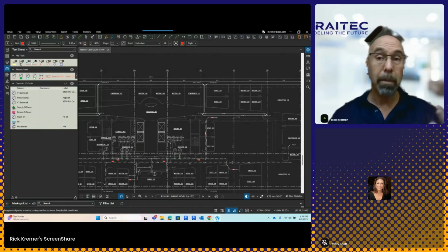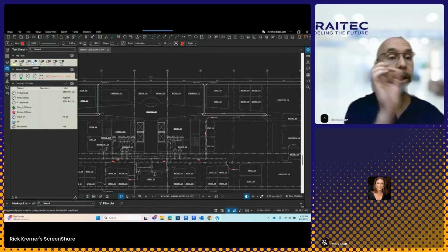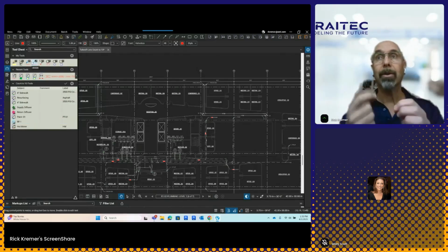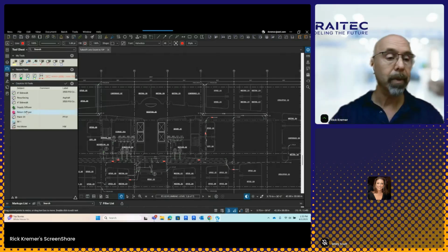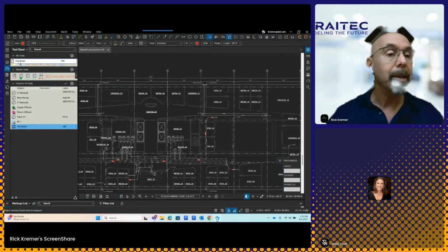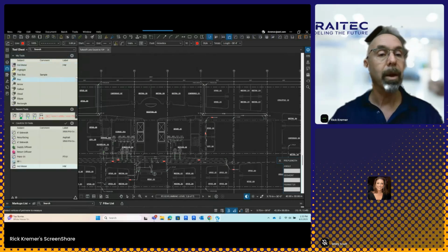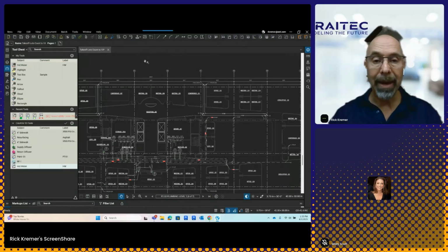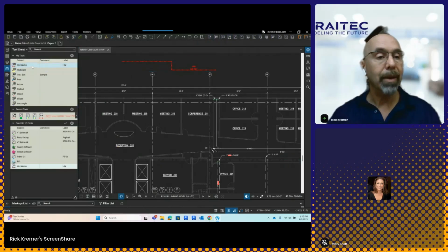If you'll notice over here under My Tools, there's 1 through 8. You might not see it on my screen, but on yours, under My Tools, this is an area where you can use your shortcut keys on your keyboard to initiate any of this information. So what I'm going to do is temporarily left click and drag and place this right over here, and it's now number 1. You're number 1. Over here's hot water, number 1. So what this means is if I press number 1 on my keyboard, I'm now drawing hot water. You see that without activating that.